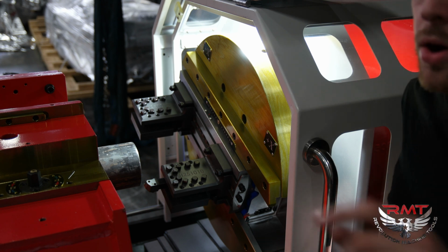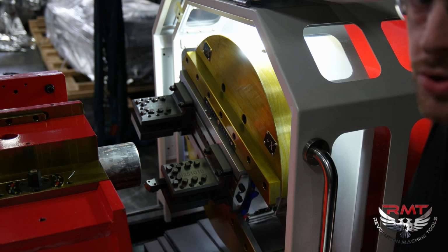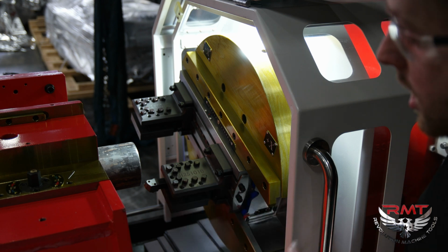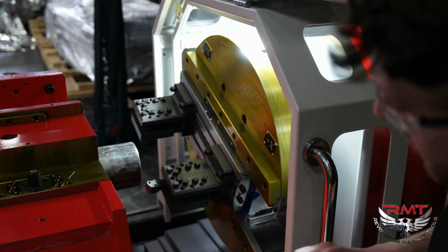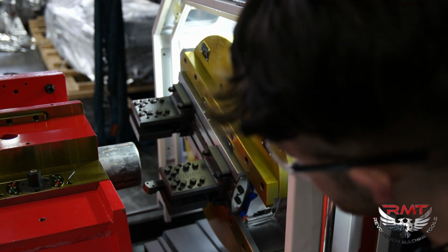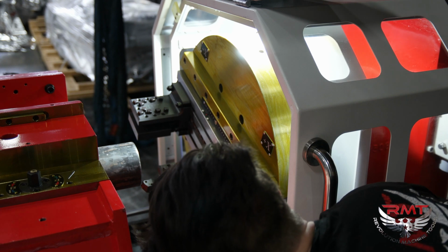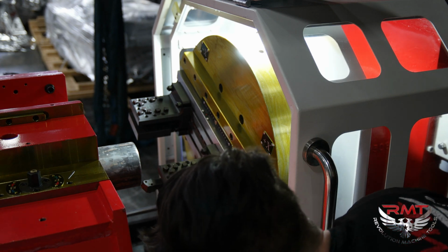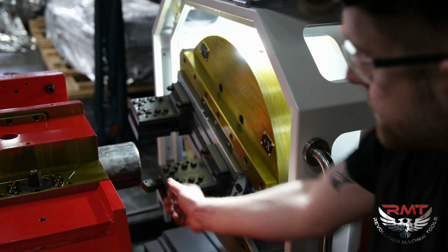That means, though, that I'm not going to touch my tool off in Z. For any other tool that is not the reference tool, you would touch off in Z. But what that would look like is I'm going to come out a little bit, and I'm basically just going to go in until it looks really, really close that my cutting edge is lined up with my material.